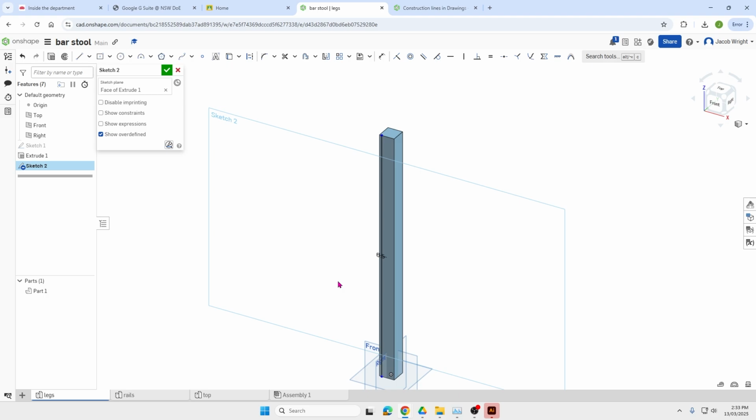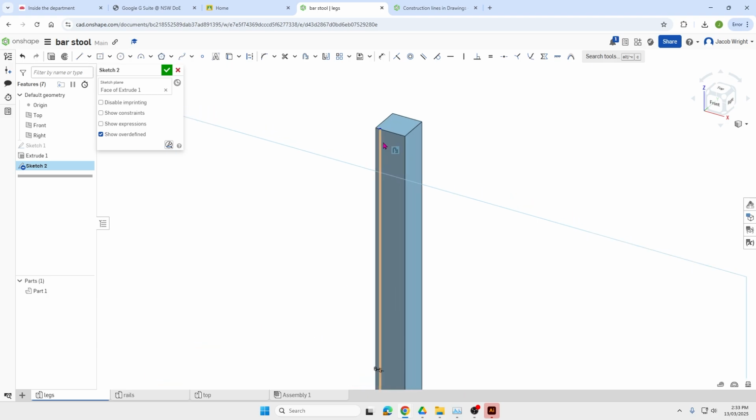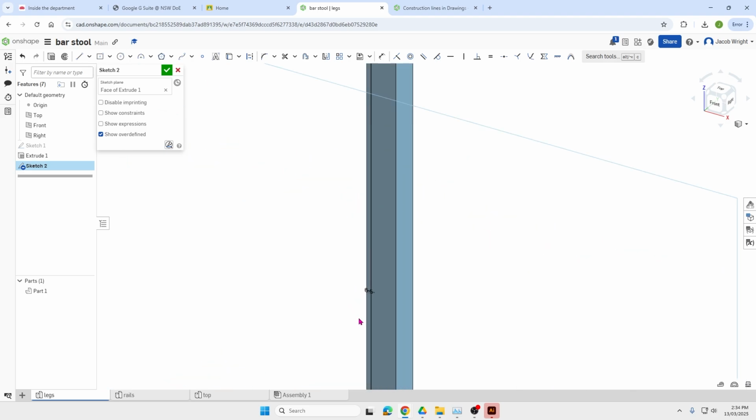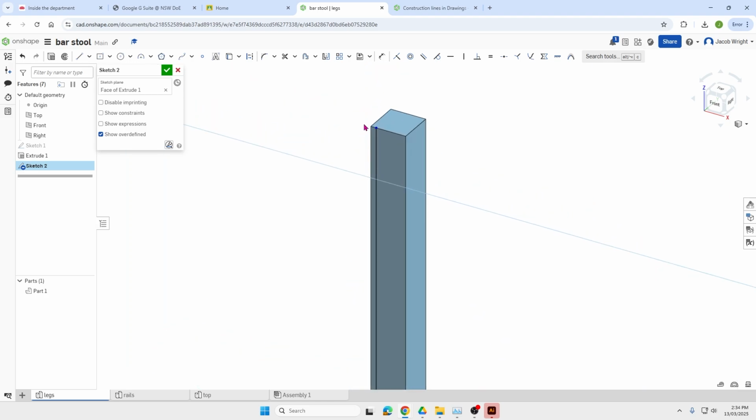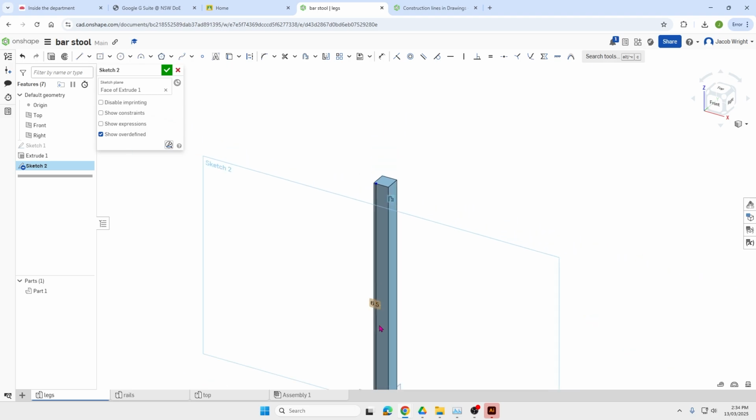6.5. Okay, so now I know as long as I make the mortise starting from this line, the rail will finish perfectly flush with the outside. If I don't want it to finish flush and I want it to be inset a little bit, which I think is a more desirable look, it also allows a bit more room for error with your mortises. So if you make a mistake, it's not so obvious, whereas if you're trying to get a flush finish, it's quite obvious when you make a mistake because there'll be a step.